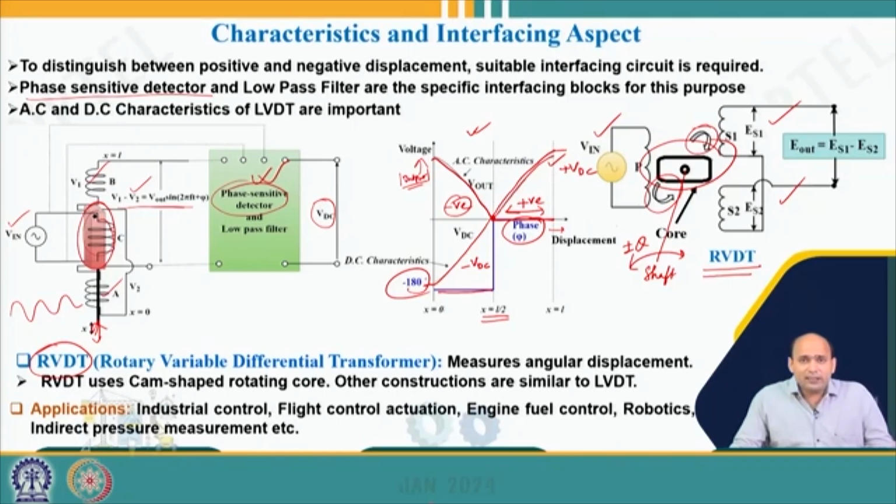You remember that in the previous class we discussed some pressure sensor with a diaphragm element, and we said the diaphragm was the primary sensing element. In order to convert that position into resistance, we connected a strain gauge on the diaphragm, and the strain gauge resistance was changing because of the applied strain. In that pressure sensor we used two elements. One was the primary diaphragm, the primary sensing element, and another was the strain gauge, the secondary sensing element, which was used to convert the displacement into resistance.